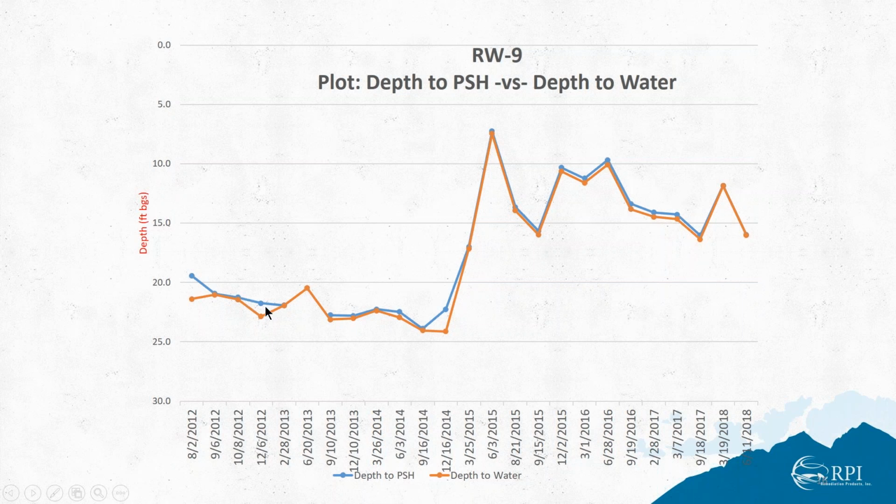We all know that there's a relationship between the depth to water and whether or not we actually see free phase in monitor wells. You can see from the plots that this is an unusual well in that almost independent of where the groundwater was, we saw free phase in the past with one exception. Free phase has been in this recovery well all along. Then we injected, and groundwater went up, and most recently it has dropped down, and yet there's no free phase there.